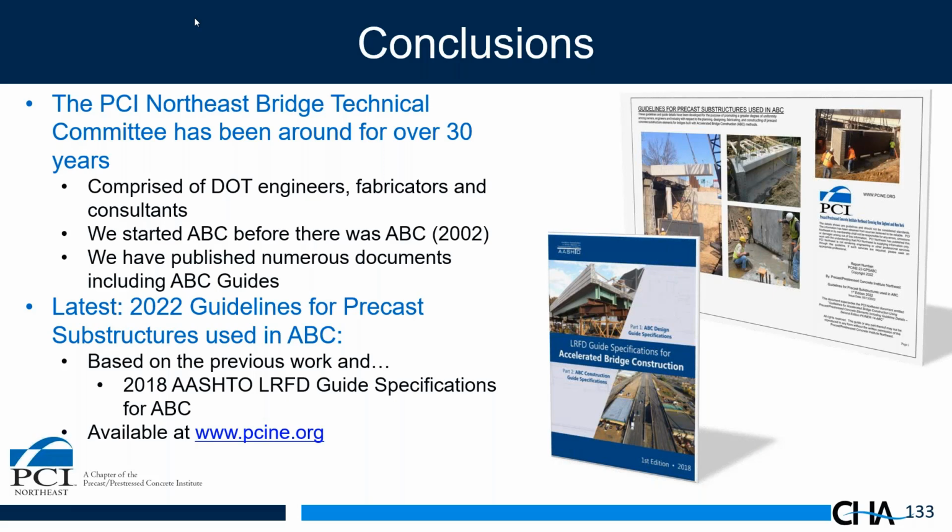So we have heard, and I know Mary Lou's told stories in Texas where contractors have proposed precast pier caps where cast in place was detailed because it was less expensive. So that's the one thing I could say when it comes to substructures. Precast pier caps are probably less expensive. I'd also say our precast integral abutment details are painfully simple. My guess is they are probably cost effective as well.